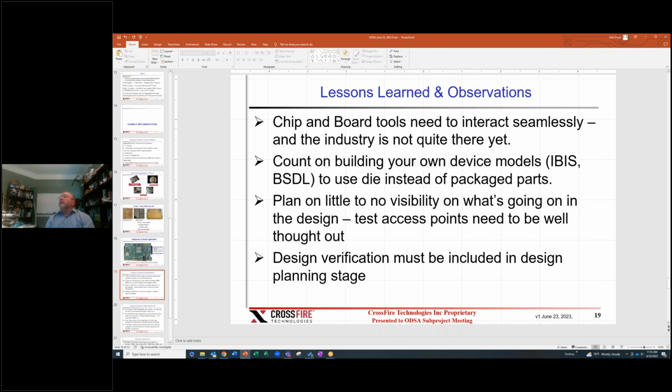Okay. All right. So when you're working with chiplets, you're working in two worlds: the chip design world and the board design world. And these are different people that think differently, and it's bad sometimes. Two experiences that we had: to do simulations, we needed IBIS models. So our FPGA vendor generated IBIS models for a particular design because the IOs are programmable.